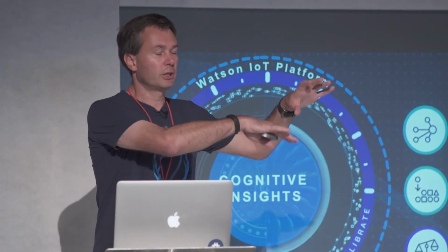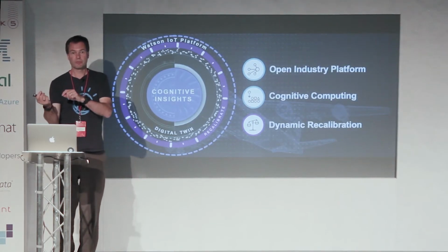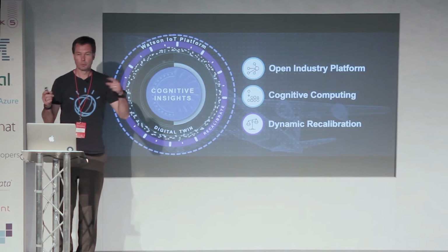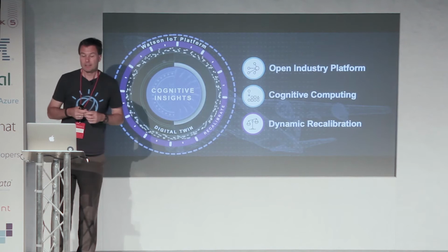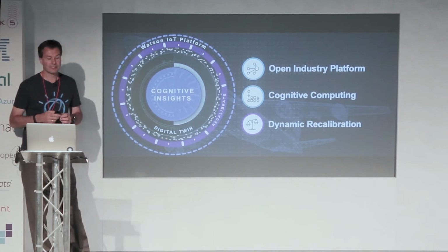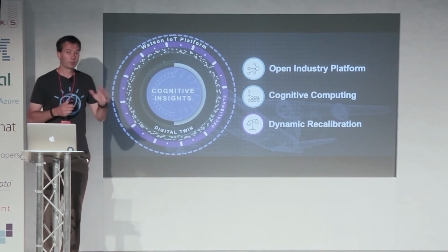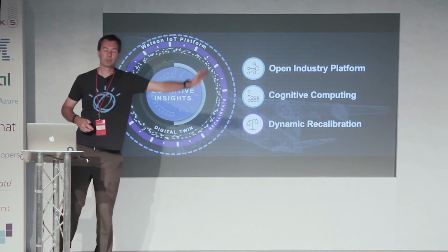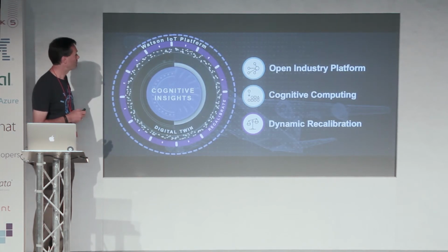So for example, in my house, there's a kind of digital twin based on the current consumption of some of the appliances, and that calculates at any given time what the total power consumption of the house should be. If I compare that with my energy monitor and it's different, I can go, we must have missed something out, or maybe there's something that's triggering in the model that's not in the real world, or vice versa, and I can then debug it to find out what's wrong. So that dynamic recalibration could be automatic, could be manual, but you've always got to have the checks and balances in place to make sure that your digital twin's not going off over here while your physical system's going off over there. And that's part of the development and tuning process.